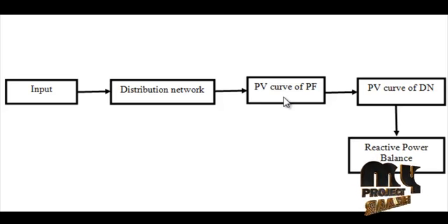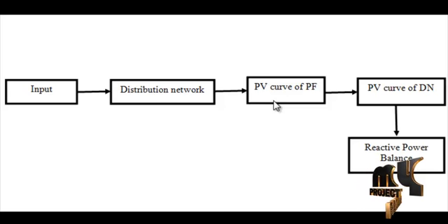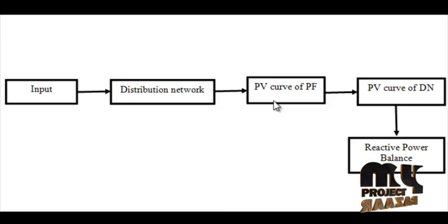Now, the PV curve of power factor: decreasing the load power factor will not only lead to lower voltage quality and increased grid loss, but also reduce the grid transmission power. The PV curve with KQP3 equaling 0.2, 0.4, 0.6, 0.8 respectively. The ratio of reactive with respect to active power increases due to decreased power factor. The maximum power transmitted from grid to the bus 3 is reduced. The KQP3 is the ratio of Q3 with respect to P3.